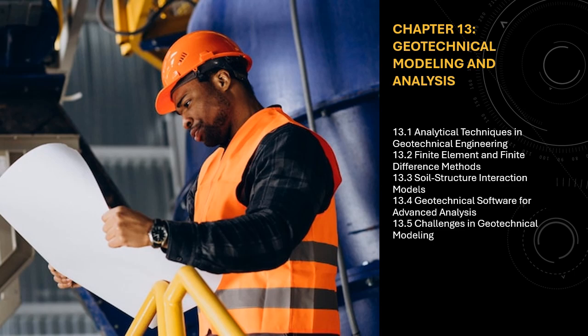13.5.7 Validation and calibration of models. Once a geotechnical model has been constructed, it must be validated against real-world data to ensure its accuracy. This involves comparing model predictions with field observations, such as settlement, pore water pressure, or soil displacement.